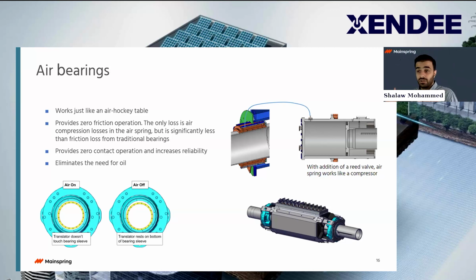It's such a light metal, so it can move back and forth on a cushion of air. In a traditional engine, the connecting rod where it connects to the crankshaft experiences roughly 100,000 Newton of force. So that's why air bearings are very intrinsic to our design. It's not only the air bearing itself, it's how we design the entire system of the translator.